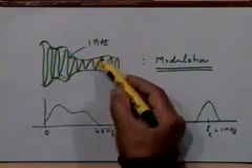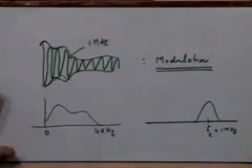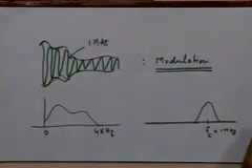So if I ensure the safety of the amplitude in the signal, can I get back the original signal information? That's the whole idea, that you must do this modulation in such a manner that it is possible for the receiver to get back the information, right? So it is obviously implied here that at the receiver I will have an appropriate demodulator which will undo what the modulator did, right? So it will be able to extract the information of interest, which is in the amplitude of the signal, and convert this into the actual signal itself which was intended to be transmitted in the first instance, right?